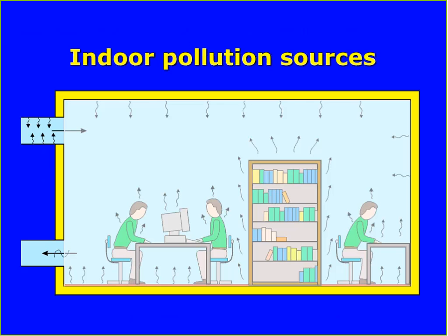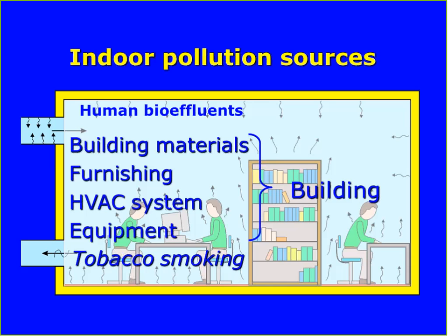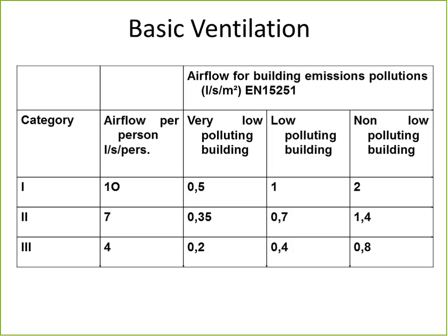Now, we also know that it's not only people who pollute the indoor environment. We also have a lot of building materials which have outgassing and also influence the perceived air quality or the odor in the room, so we have to take that into account. We also earlier took into account if people were smoking or not, but we do not anymore. So the ventilation rate we are talking about is for rooms without smoking. And for that purpose, we have another table with the required airflow to dilute emissions from buildings.